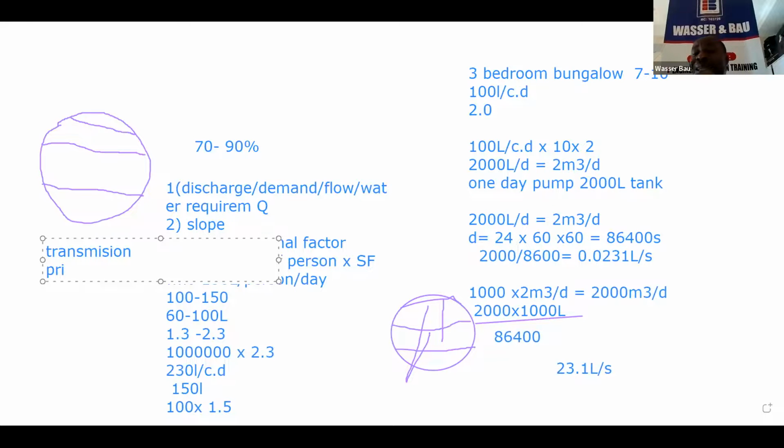Then once it enters the house, they cannot use 1.5 inch or 1 inch pipe, because the mains is so important that if there is a pressure loss in the mains, the secondary are gone. So you can use a big pipe for the main pipe. Then the secondary pipe can just come using reducers and attach to the mains.